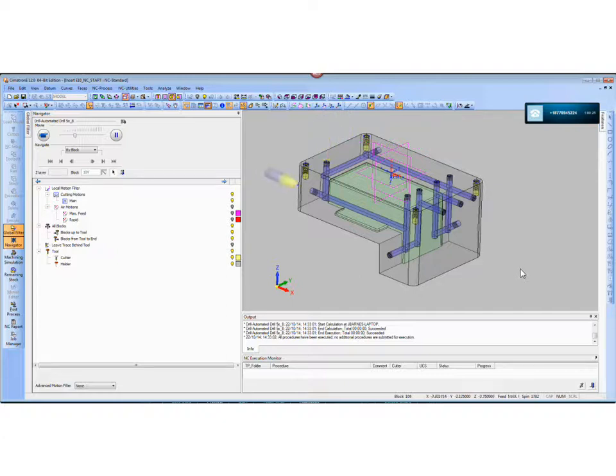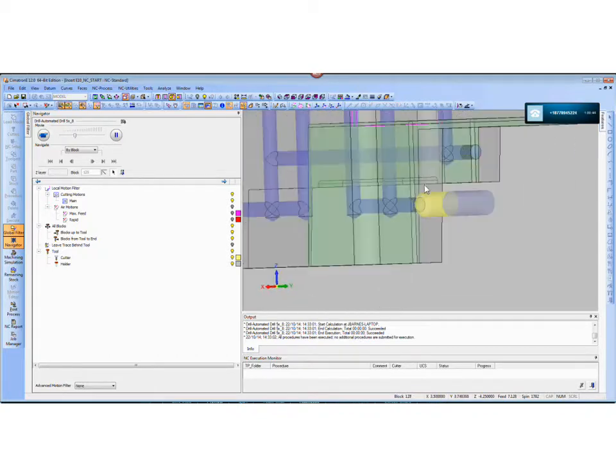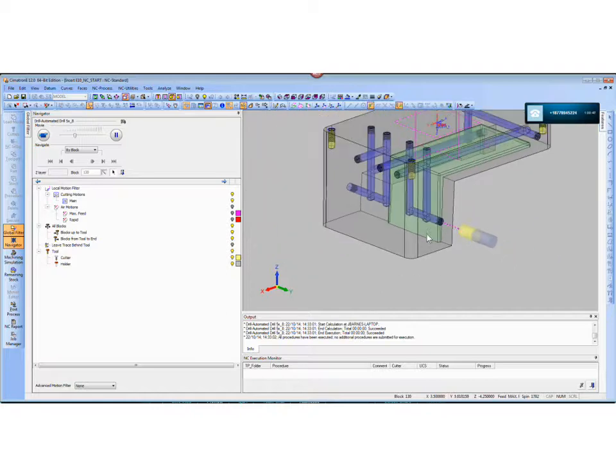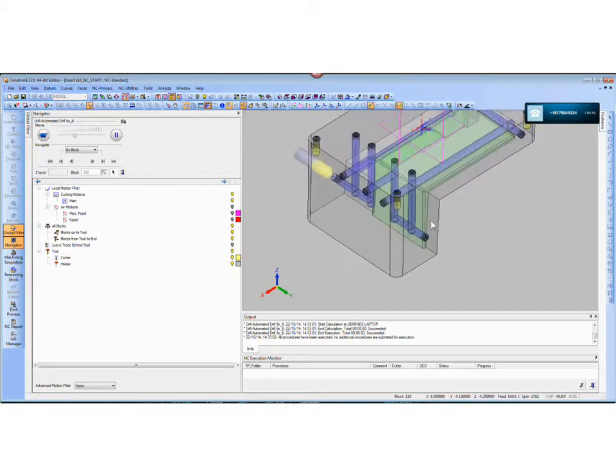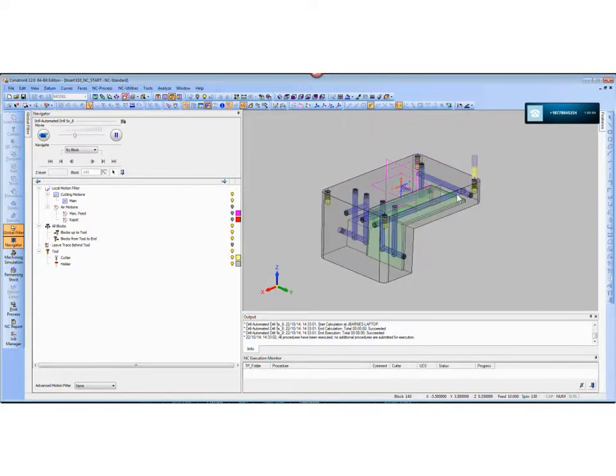Now these water lines I am processing with a starter drill, for 2 reasons. Number one, I want to have a big chamfer lead in on these holes. I think that's an advantage. And secondly, you're going to see some logic being used here in a minute. This is the tap drill coming in and tapping these holes. But in a second, you're going to see that not all these holes are drilled in the same way. Even though I use the same sequence, the sequence can have logic built into it, and I'll explain that in just a second.